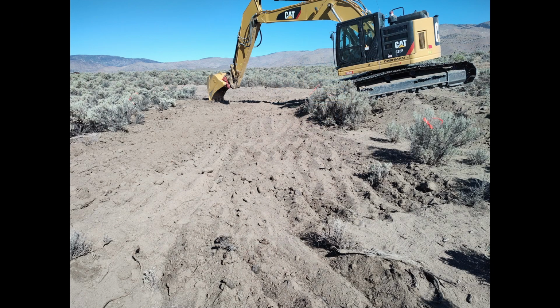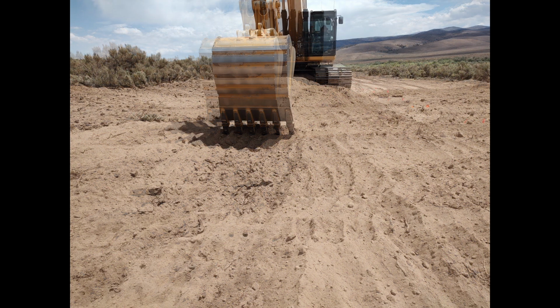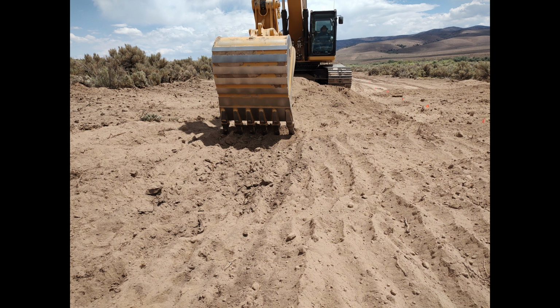We spread the soil that was removed beyond the lower edge of the spillway being built. The soil was spread and fanned out. It was not shaped into a berm. The uphill edge of the spillway was sloped, so there would be no ridge or berm that prevented runoff from entering the spillway. Don Smith used the teeth on the bucket of the excavator to loosen and to rake the spillway to a depth of 12 inches so that water would soak into the ground.